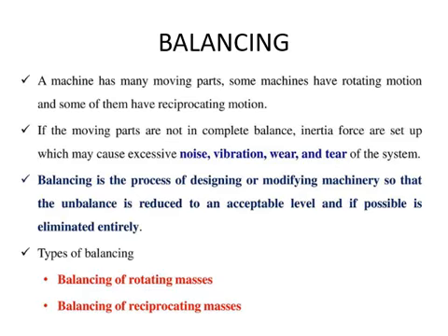Due to these unbalanced forces, the machines will vibrate. As a result of these vibrations, the running life of the machines will come down. To overcome this vibration, we go for balancing. Balancing is the process of designing or modifying machinery so that the unbalance is reduced to an acceptable level, and if it is possible, eliminated entirely.